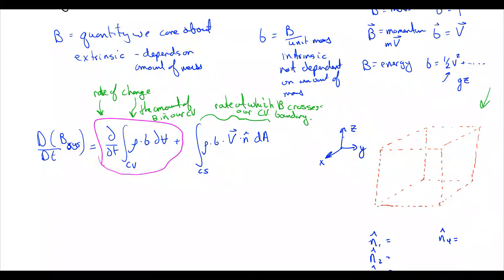So if you're pouring water in, the velocity of that water times the area times the density is going to give you the mass flow rate of that liquid entering the bucket, and that's going to be equal to the rate of change of water inside of the bucket. It seems reductive to say it that way, but that's really all that this equation is saying.